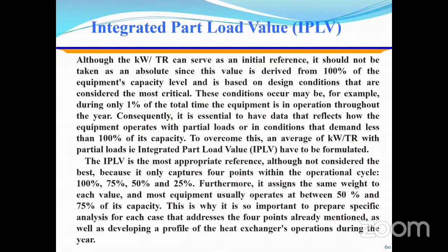Integrated part load value. Although the kilowatt per TR can serve as an initial reference, it should not be taken as an absolute, since this value is derived from 100% of the equipment's capacity level and is based on design conditions that are considered the most critical. These conditions occur maybe, for example, during only 1% of the total time the equipment is in operation throughout the year.